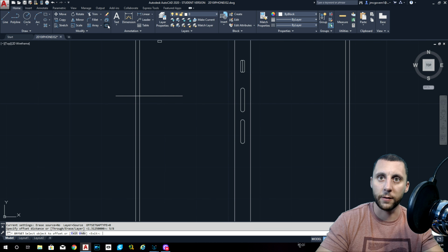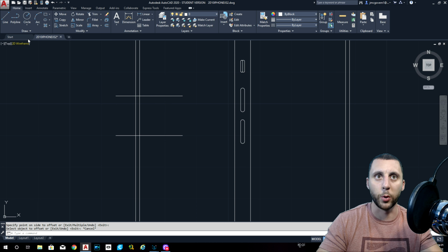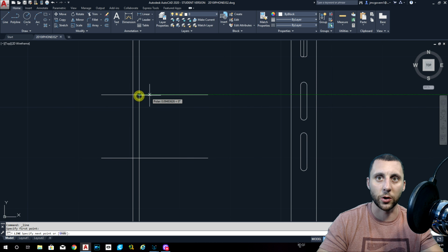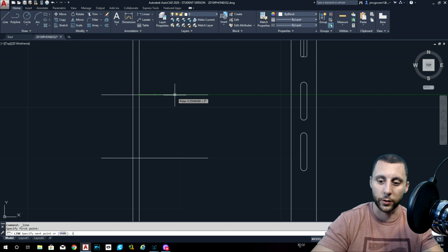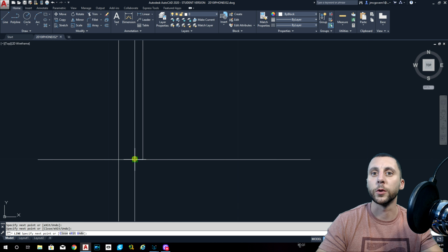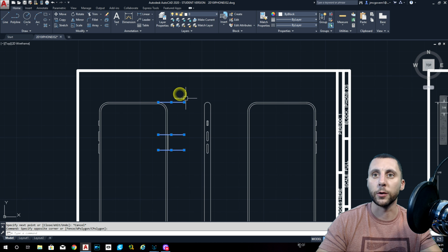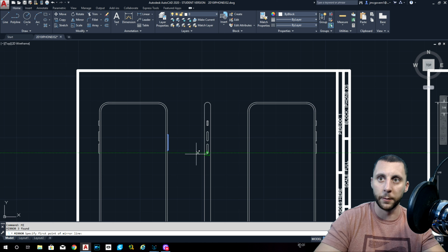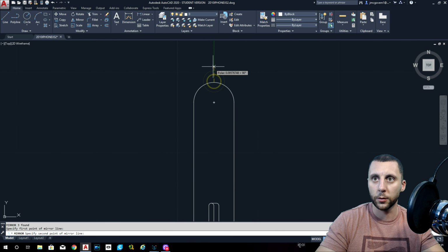Offset 5/8. Both these lines are going to be erased. So we start right here, go out on the green line 1/32, come down, go in. Now we get rid of these lines. We have our button. Same thing, we'll take that button and mirror it over that point.